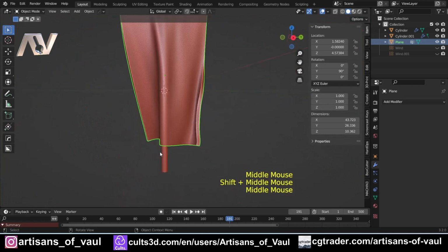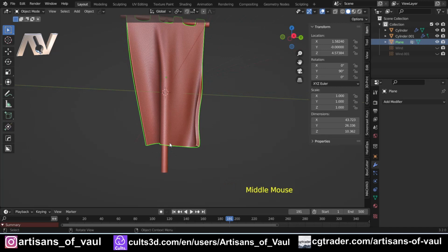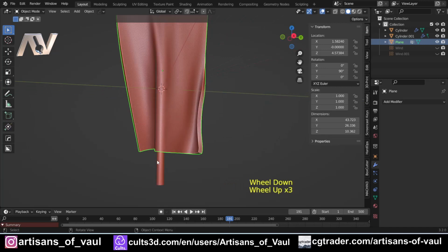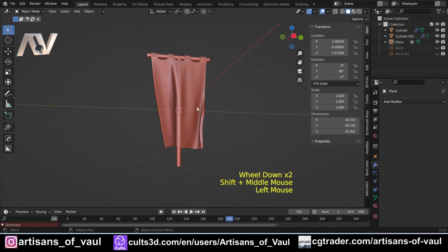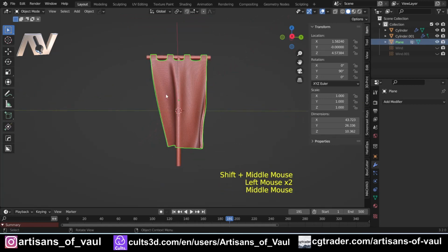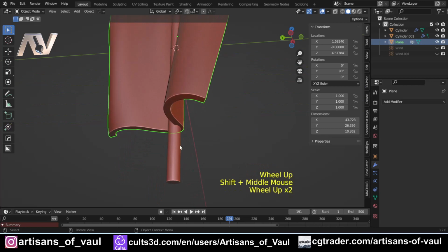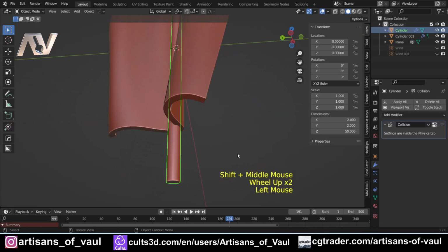But it's going to create a notable weak point here, which with some weight above it, is potentially a point it's going to snap. Because of that, I very rarely 3D print this as one solid object. I did it in the past, it looked great, and then it snapped. So that's up to you if you want to take that risk. My personal solution to this is I take this banner and I increase the thickness to, let's say, 2.2 on all sides.